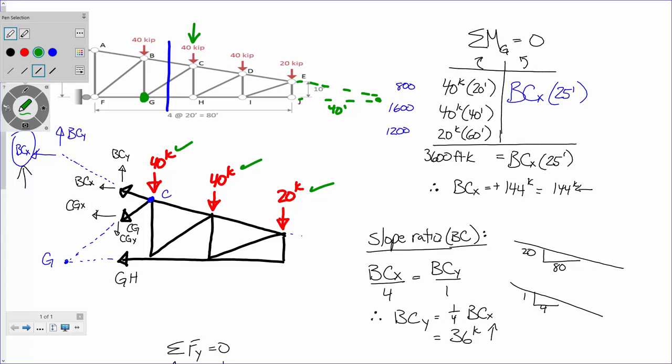But there's something to be said about us just going through the rigmarole of doing a section analysis, using equilibrium, sum of moments, sum of forces in the y direction, slope ratios, to get us thinking about structural analysis. And I thought that exercise might be pretty good for us. All right. Does anybody have any questions about this problem? Now, we have another truss problem coming up where we're going to do truss deflections. And if you all remember from structural analysis, in order to calculate truss deflections, you have to use the unit load method. You put a 1 kip force on there, and you have to do 2 truss analyses. So we're going to have more experience with truss analysis. So don't worry. We'll have plenty of experience.